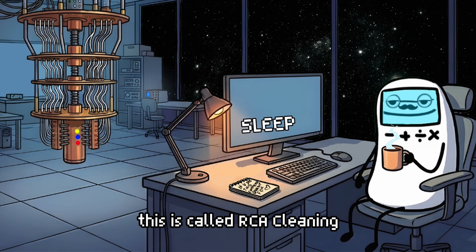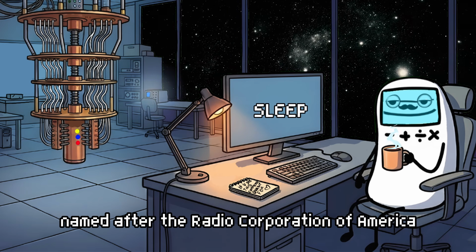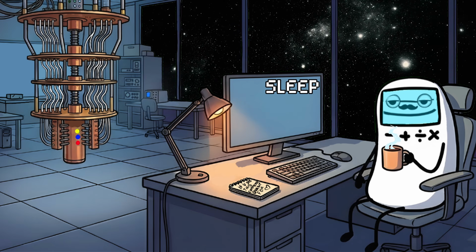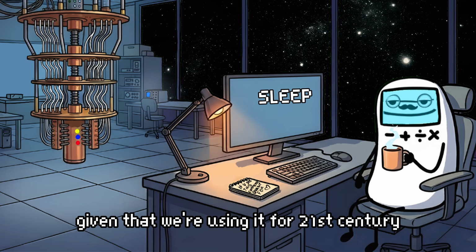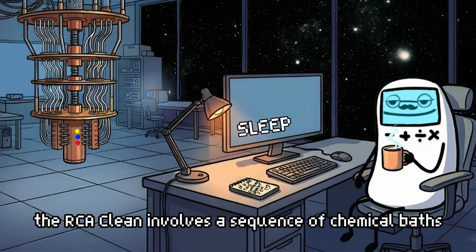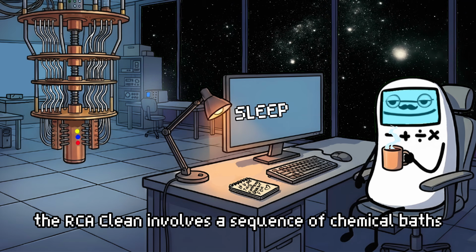This is called RCA cleaning, named after the Radio Corporation of America, where it was developed back in the 1960s, which is kind of funny given that we're using it for 21st century quantum computing. The RCA clean involves a sequence of chemical baths.